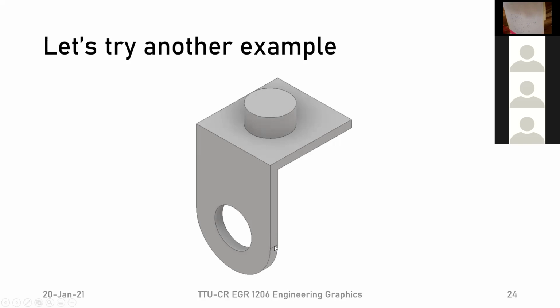There's nothing for us to see because the start of a circle is a gradual thing, right? So there's no edge that we can see. Any edge that we draw on our drawing needs to be in the actual object as well, right? So that's why we don't say there's something here, where our curving starts. There's nothing to show from this side, so we don't move that.